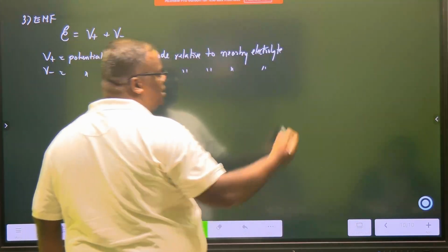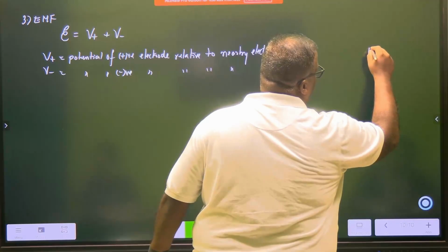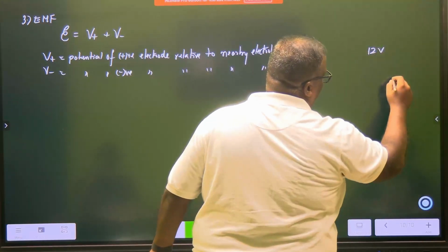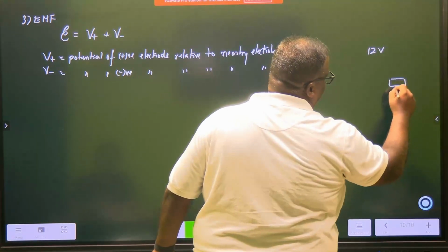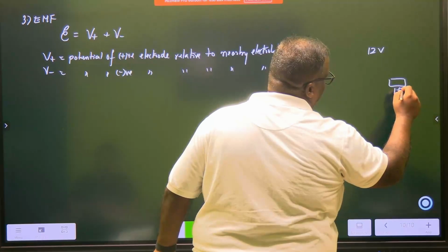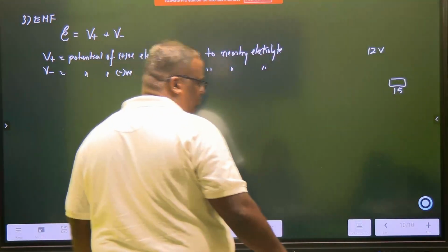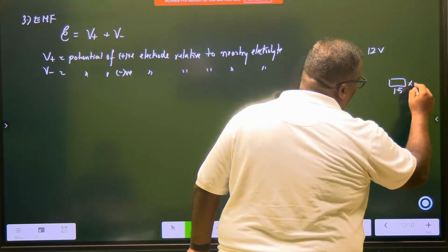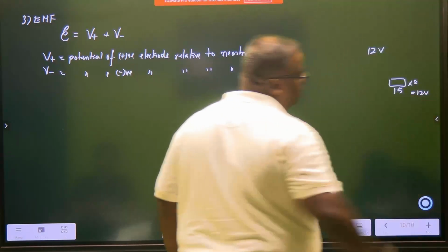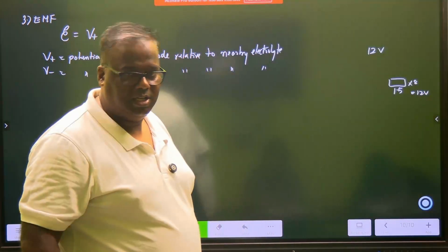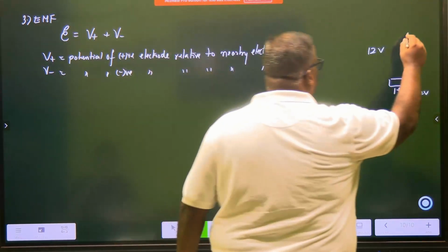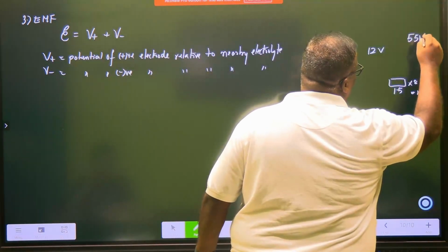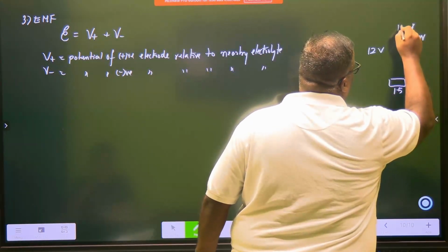That's the reason you should always connect a device to a suitable source. For example, a car battery is 12 volts, and if I take that Duracell cell, how much is this? 1.5. So if I connect 8 of these in series, I'm generating 12 volts. Got it? A Maruti 800 headlamp is a 55 watt headlamp which runs at 12 volt.